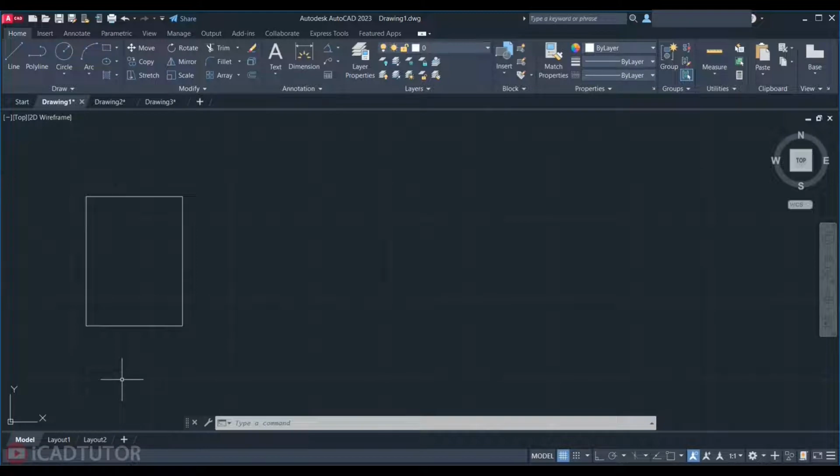Now I want to activate 2 drawing aids and to draw this room by using these drawing aids. Let's see. The first one is ortho mode. The shortcut is F8. Press F8 to activate. Press again to deactivate. I activate it. Now I press enter. The last tool is active now.